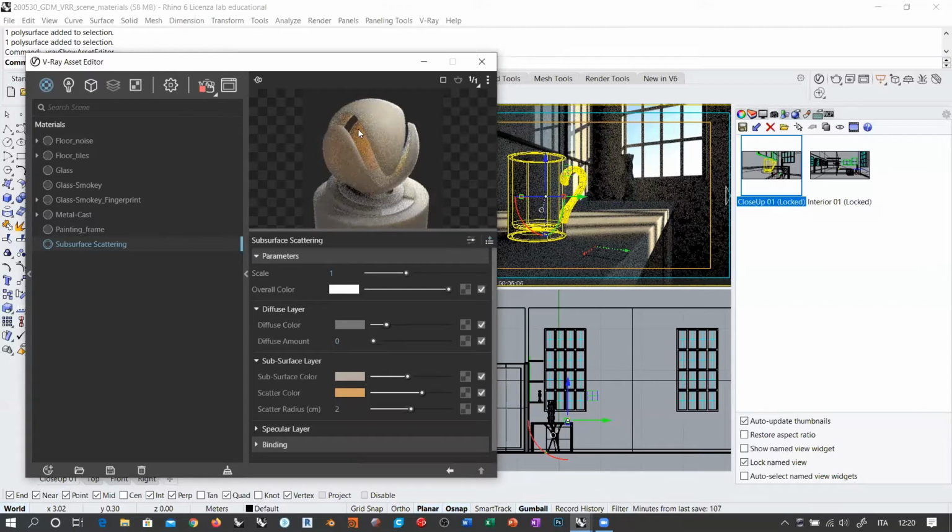But also, if you take a look at the inside, imagine that there is some light on the back or somewhere, and you see that through the material you have this kind of shiny pinkish color. You see, this is the light passing through the object and filtering on the opposite face and creating this kind of luminescence here. Also on the edges you have this kind of semi-transparency or translucency, which is defined by another color. Okay, so this is what happens with a subsurface scattering material.